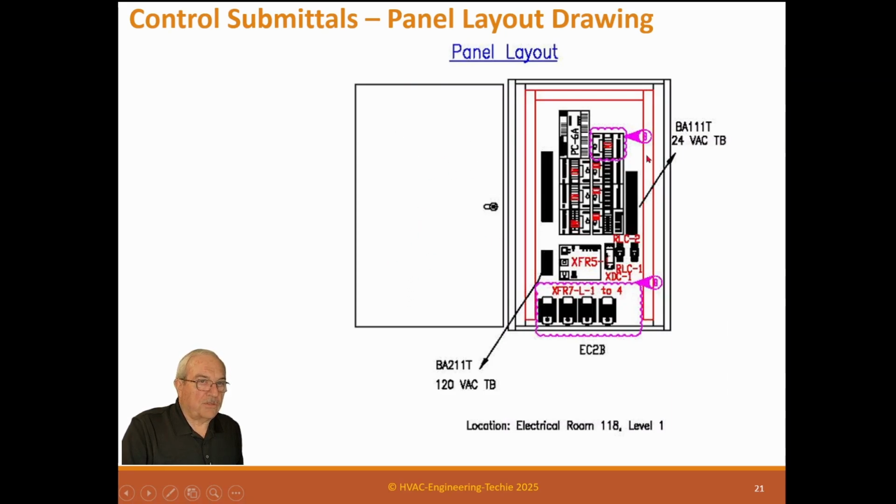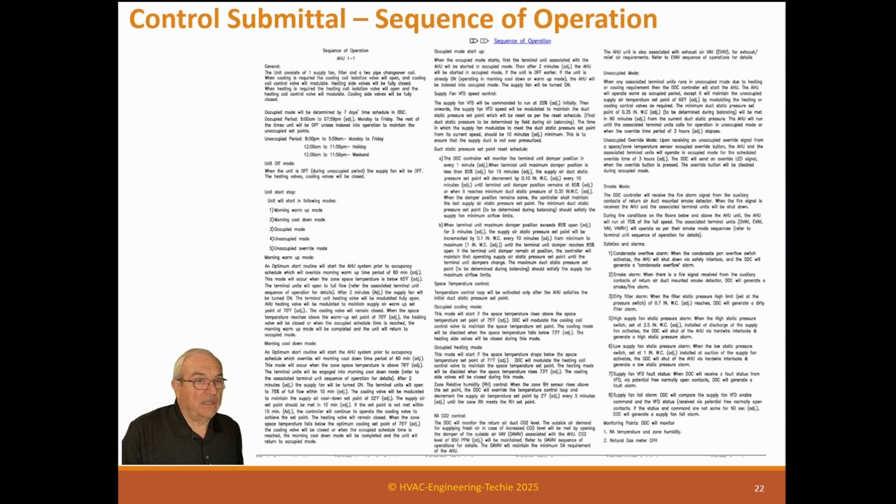So this happens to show gutters around the outside, and wire gutters are important to keep the wires from being messy inside the panel, because what happens is as a commissioner, I would look at these panels to make sure it's going to be good for an operator. Can an operator determine what wire goes where and to what device, in case he has to troubleshoot it? So these panel drawings will tell him that.